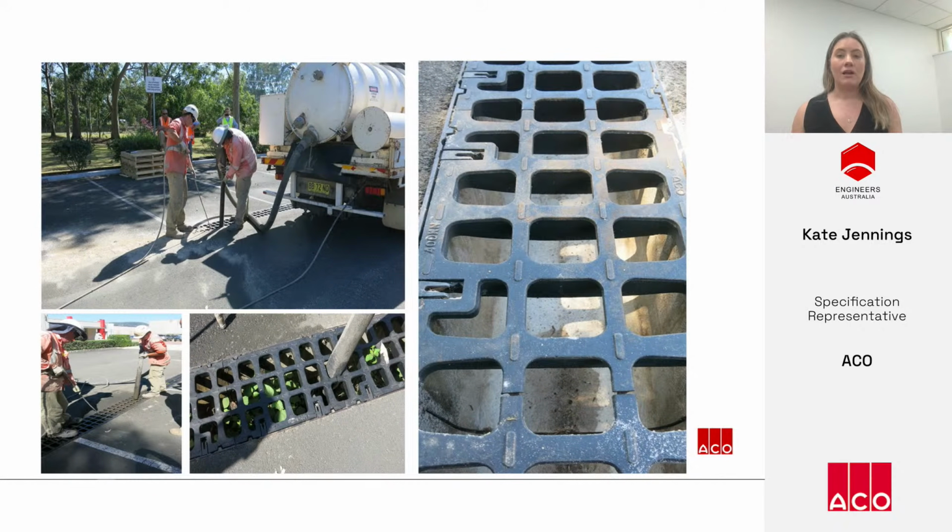High intake grates with large slot sizes also allow the channel to be cleaned without actually having to remove the grates. A sucker truck with a high pressure washer is used to break up any sediment within the channel and wash it down to the vacuum pump, which sucks up all of the suspended silt into the truck. All of this can be done without unlocking and removing any of the grates.